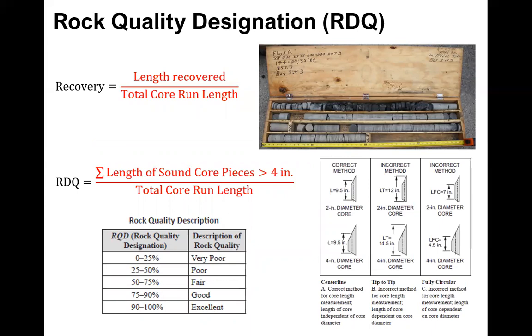Do you have a question? Yeah, that directional drilling, that's for petroleum. That's really common in petroleum because then you can get a wider footprint too. These layers are horizontal, so if you go sideways, you can get any seams in a different direction. So they get a little bit more understanding of it. For geotech, most of the time, we're not going 1,000, 2,000 feet deep like the petroleum people are. So we just go vertical.